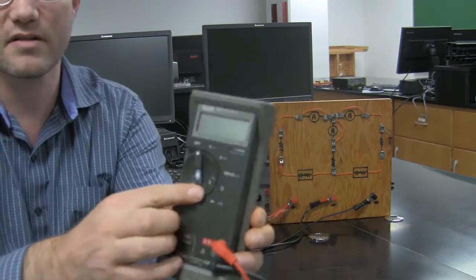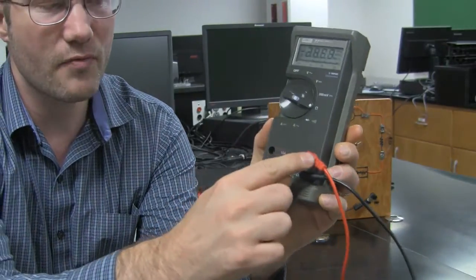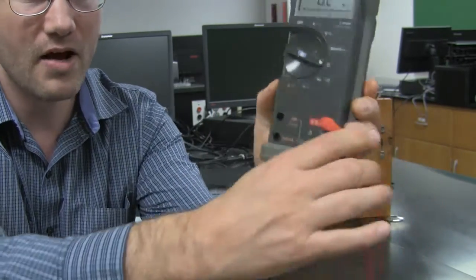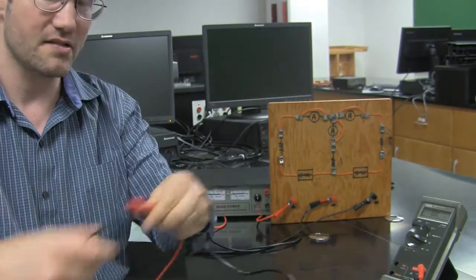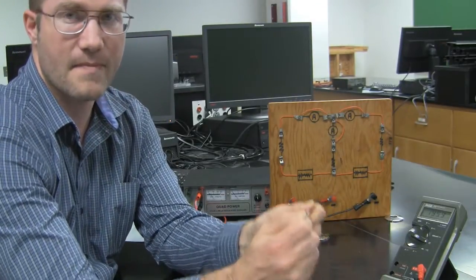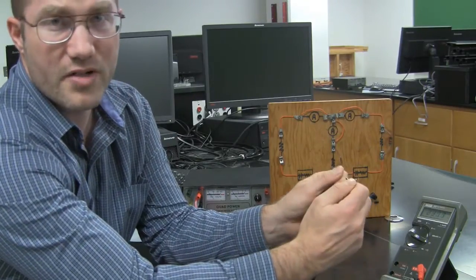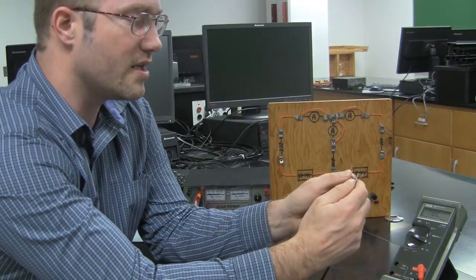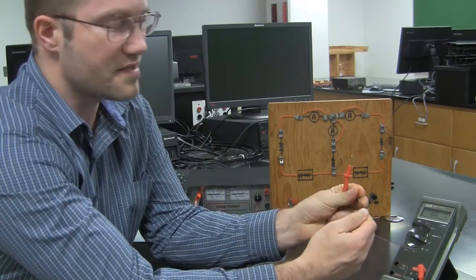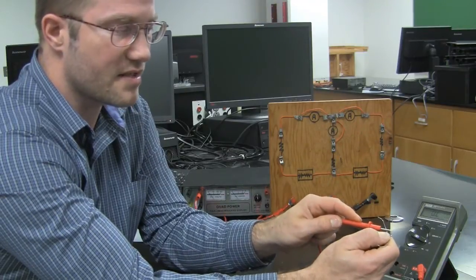I'll take my voltmeter and turn it around to the ohm setting, and then with the red lead in the volt-ohm jack and the black lead in the common, I would take these probes and read the resistance. I just grab it just like that. I can put my thumb strongly across it. Now you think, oh, when you do that, Dr. Kottman, you are putting that resistor in parallel with yourself. That's true, but I'm a very large resistor, and so it's still going to read a pretty true resistance. You can bypass that, but you can't get as good a grip on it.